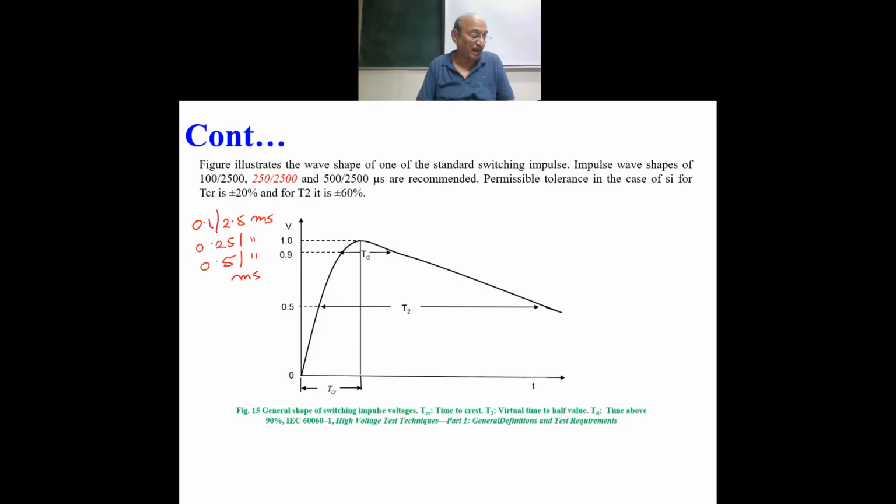And that is the reason, as we have learned also, BIL and SIL. BIL is the basic insulation level that is applicable up to a rated voltage of 400 kV. But beyond 400 kV, we have already gone much beyond 400 kV in transmission lines, and transformers are also needed there. So at so many places, mainly for transmission purposes, beyond 400 kV up to 800 kV AC, and we have gone to 800 kV plus minus DC, and 1150 kV transmission line voltage is also being practiced.